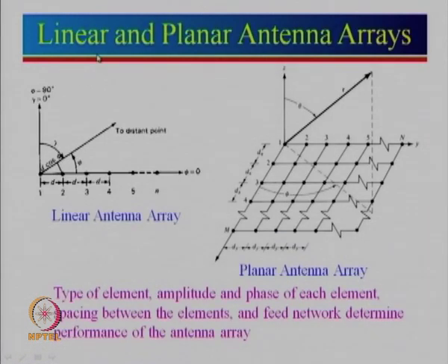Then we will talk about linear and planar arrays and why we need arrays. Just to tell you, we have discussed the dipole antenna, monopole antenna, slot antenna and loop antenna. Majority of the time the gain of these antennas is just about 2 dB, or if you take a very large dipole antenna, it can be up to 3 to 4 to 5 dB. But what if we want a very large gain?